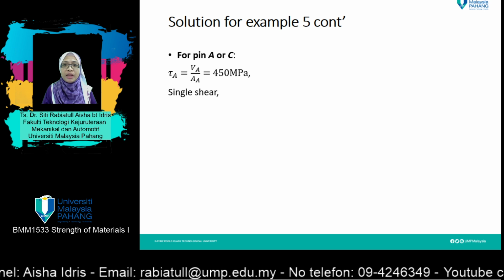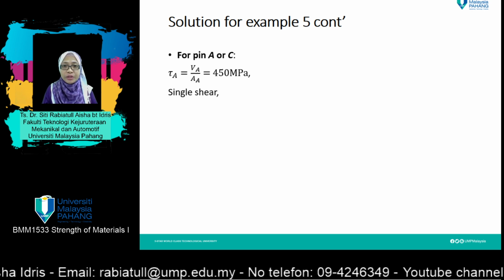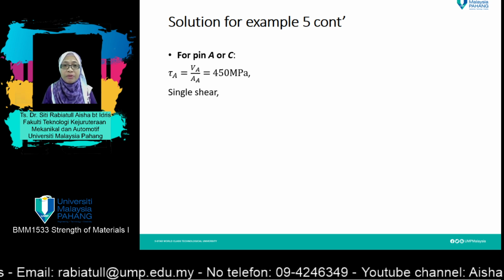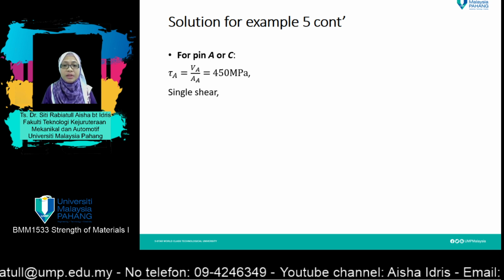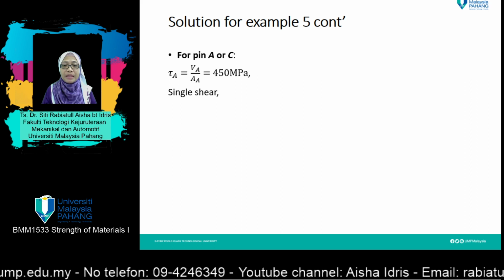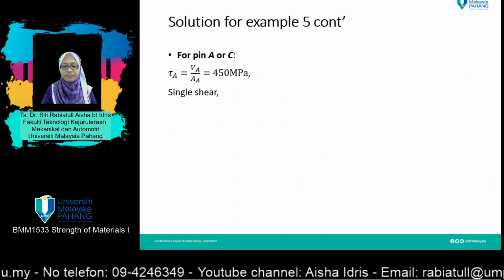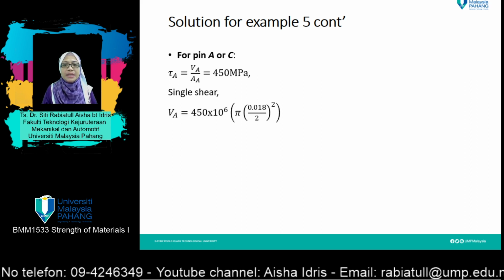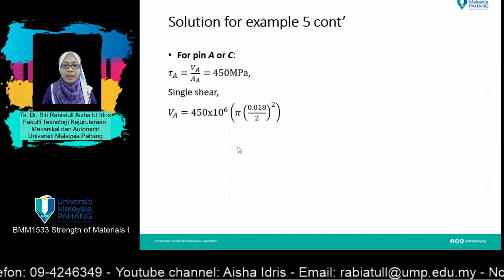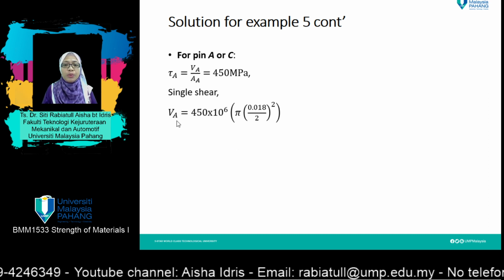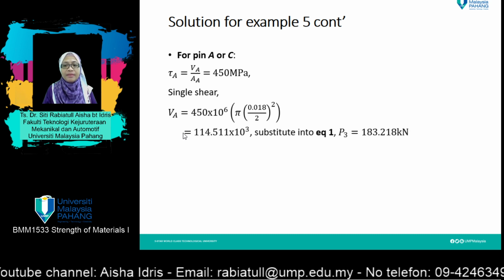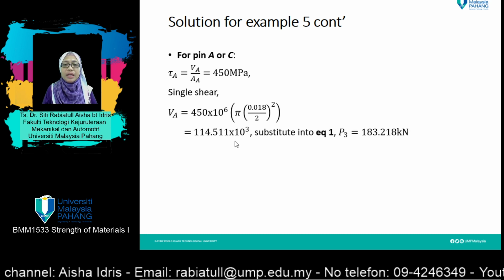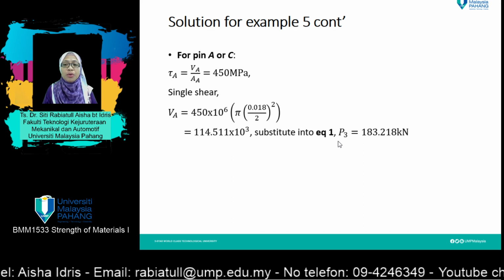And we know that this is a single shear. Please refer back to the original diagram. From there, you'll know the shear force acting on that pin is single shear. So substituting all the information into the formula, you will get the value of shear stress at pin A. And this value needs to be substituted into equation 1.